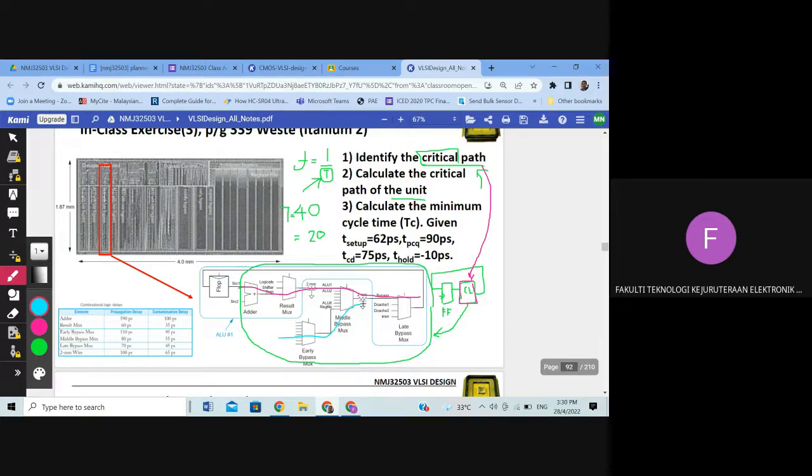In terms of number of components, we can identify here: number one, the adder, number two, component number three, and component number four, plus the delay of a wire. This is modeled as a 2 millimeter wire delay. So this is four components.